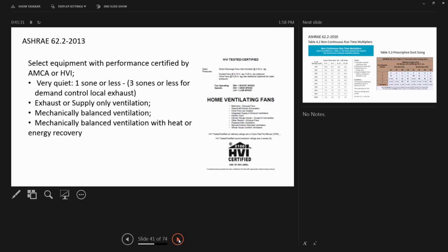So you're losing your thermal performance. ASHRAE sets up that if you have X amount of exhaust-only ventilation, then you have to bring a minimum amount of fresh air in, and inversely, if you're bringing in X amount of fresh air, you have to exhaust this much air.